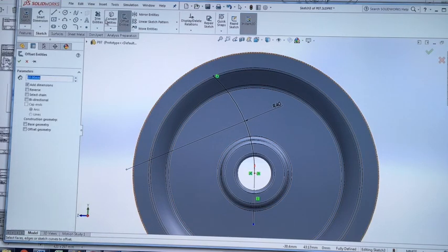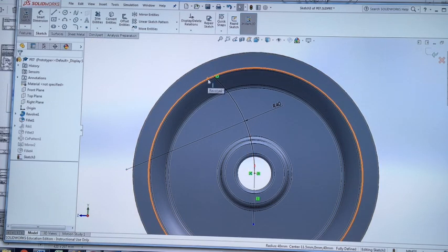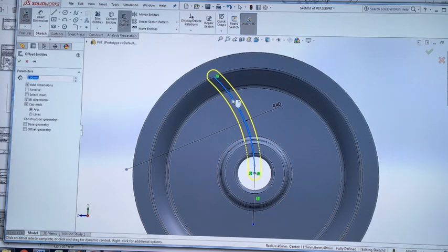And so remember that offset tool we've used before, offset entities. I can select that line and I can offset that by a certain distance and do it bi-directional and cap the ends. That's a potential option there. It may not go all the way in. I'm not going to worry too much about it actually. So I'm going to go and turn base geometry to construction as well. Press OK.